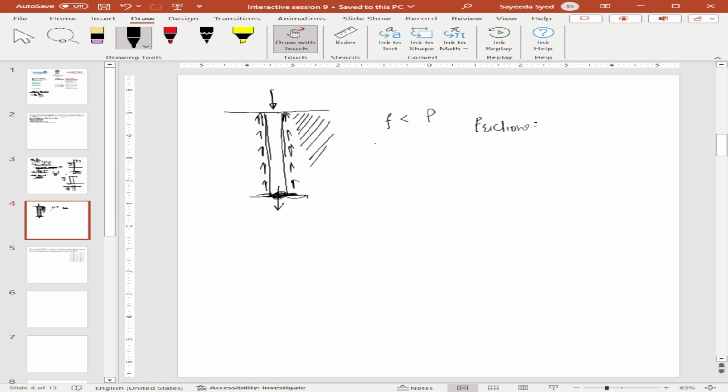But if it is a specific type of soil, like clayey soil or sandy soil, either most of the load gets transferred through frictional resistance or most through end resistance. If friction F is much greater than end resistance Q, we call it a frictional pile. If end bearing is much greater than F, we call it an end resistance pile. And if there's both, it's just a pile.